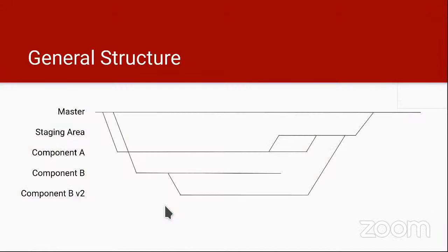So what is a repository, which is how you store your CAD? Like, how is that set up? So you see you have branches. The default branch is called master. On GitHub, this will be called main. Then you can split off from master into these branches, such as for this component, or component B, this might be your intake. And then you can say, I'm not sure about how I want to design this. I want to make a different version of this. Like say, what if the intake is horizontal instead of vertical?